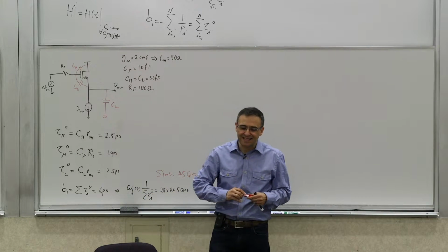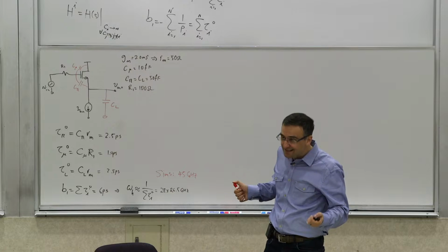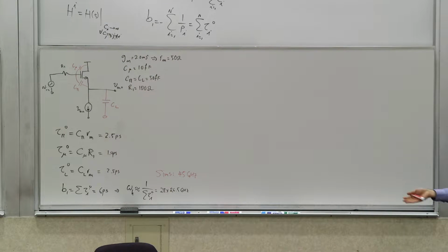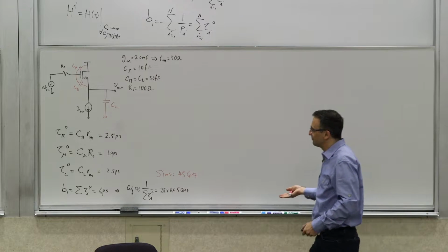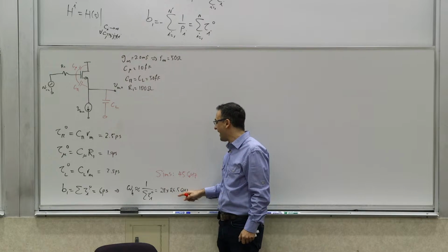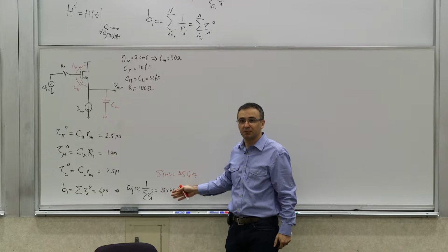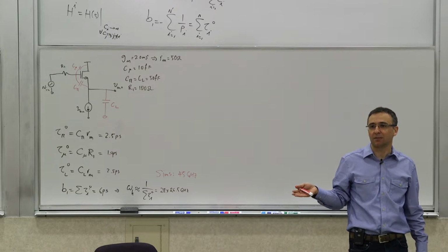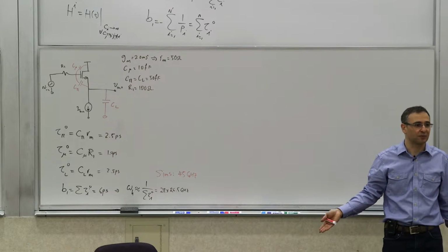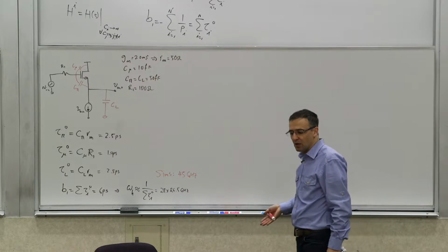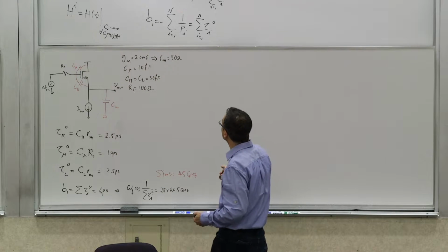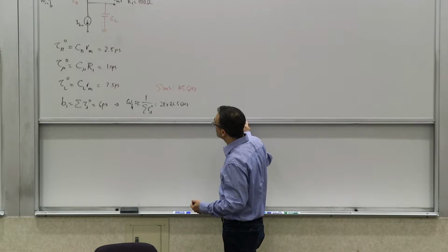So now you can see that it is conservative, all right, but if you wanted to use it for estimation of bandwidth, you have to realize that in the case of complex poles, it can actually be quite conservative. I mean, it's off by almost a factor of 2, right? So that can happen.